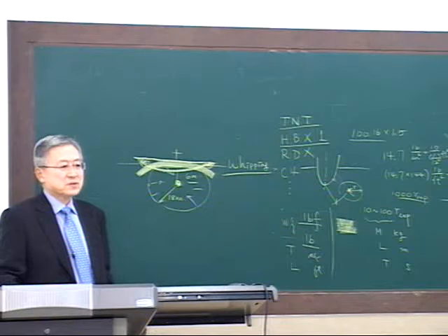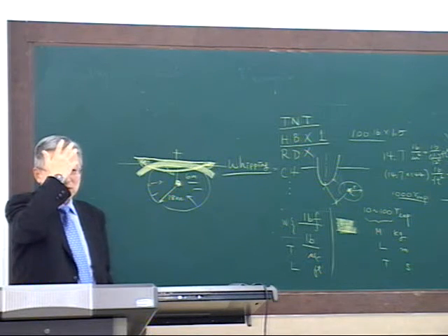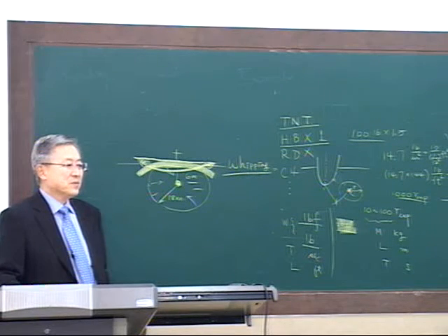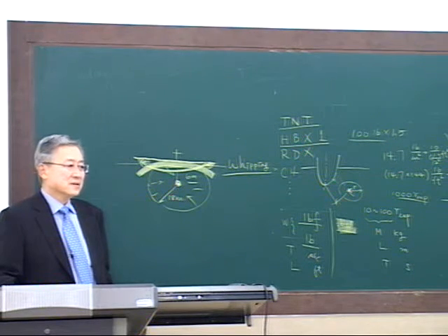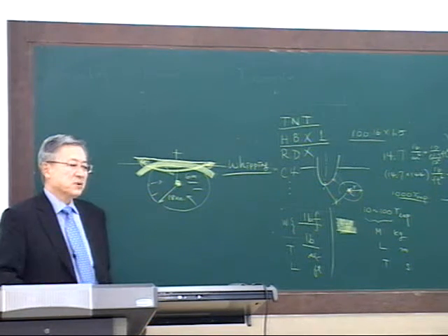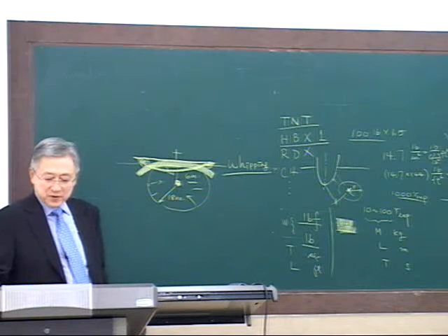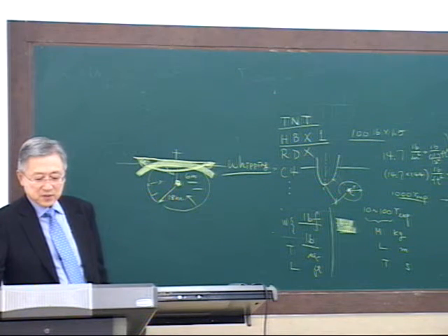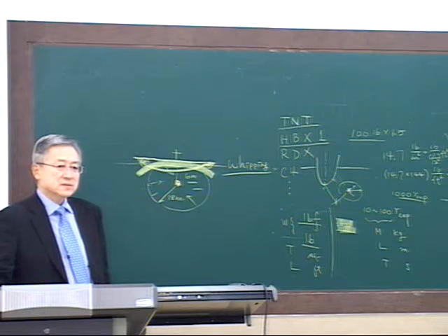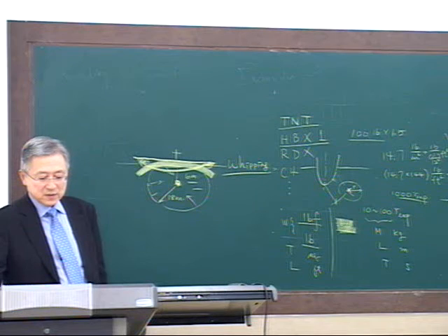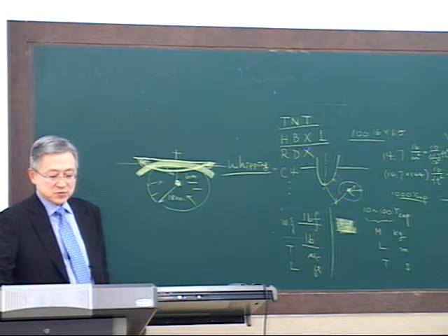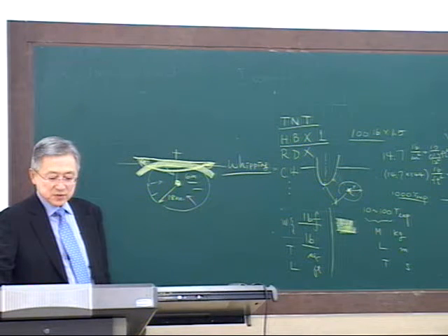It's shape dependent. Anybody has a strong interest? I have a really very thin report written by a Caltech professor some years ago. It's shape dependent. So for the sphere, this is 2/3 pi rho a cubed. So you may take a look. It's called the added mass, the added mass for the sphere, and times u.